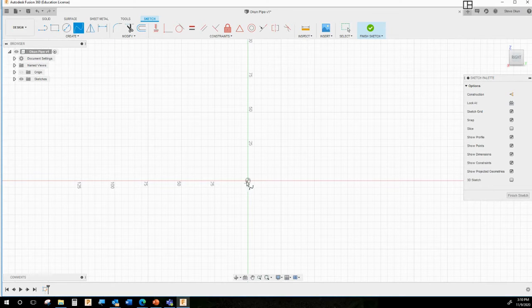Okay, so choose that. And what it's going to do is have you lay out a series of points to draw the curve, just like you would making a dot-to-dot drawing. And that's what this really is. It's like when you were a little kid and you made those little dot-to-dot drawings. It's basically that. So you've got to start at the origin for this one, or it won't work well for what we're doing, because we need to line things up on the origin. So make sure you start at the origin and click and let go of your mouse button, and then just move up. And when you create a second point, it's just going to make a straight line, because when there's only 2 points, it's a straight line.